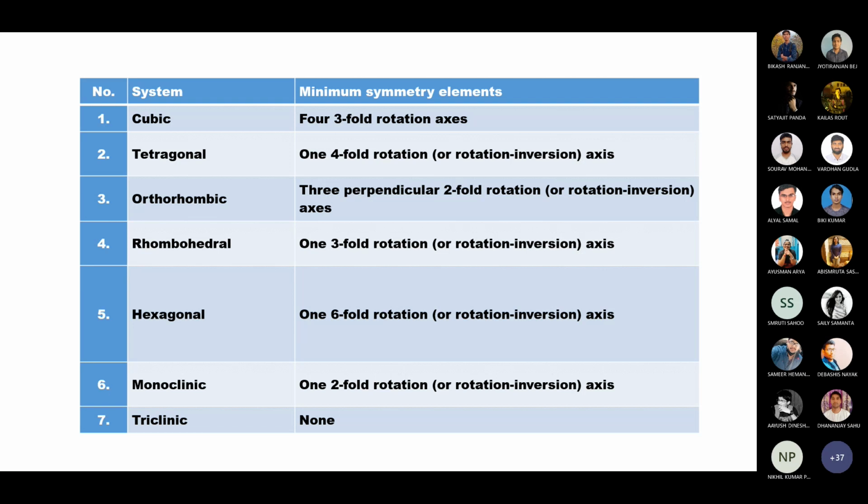So we generally concentrate on the cubic system, and sometimes the hexagonal close packed system, magnesium for example, for understanding the deformation behavior of magnesium. But mainly we are going to focus on the cubic system, body centered cubic and face centered cubic. A body centered cubic example is iron, and a face centered cubic example is aluminium or copper.